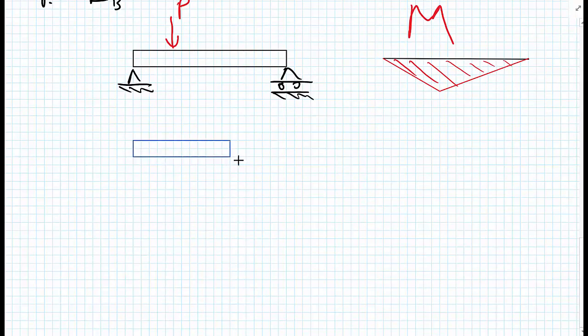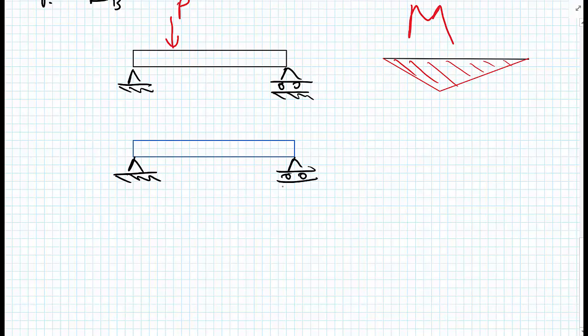So we have exactly the same structure, exactly the same boundary conditions, but to calculate the displacement, remember from the previous section of work, if we apply a unit load, I'm applying it down, could just as easily apply it upwards, I will get a deflection of the structure, and the deflection of the structure down to a unit load will be called delta BB dash.